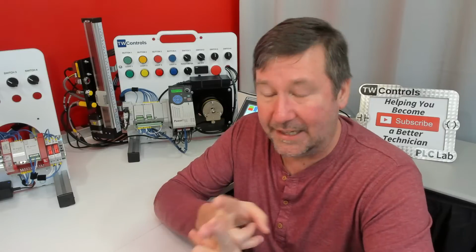It should have the incoming power. It should have the amps of the panel. It should have the largest motor load. It needs a short circuit current rating, 100%. And no one out there is doing the short circuit current rating unless they're UL. And that's a very important safety piece. Needs a drawing number, needs your basic contact info, things like that. But yeah, it's much easier than you think it is.